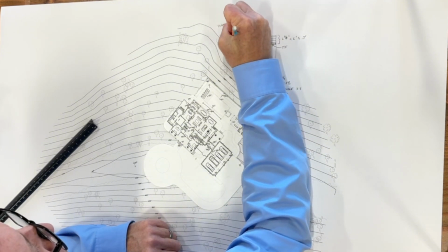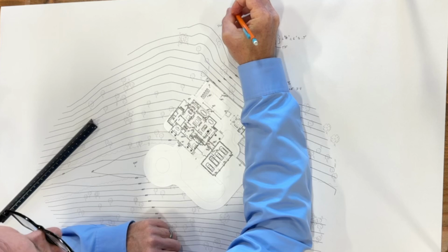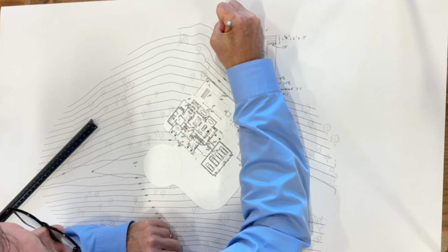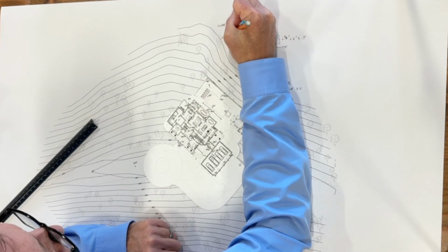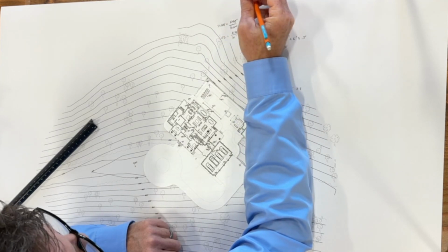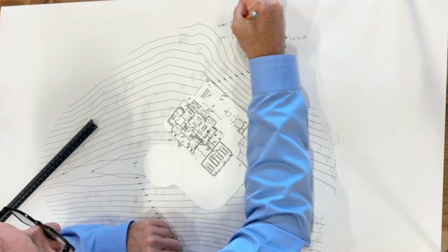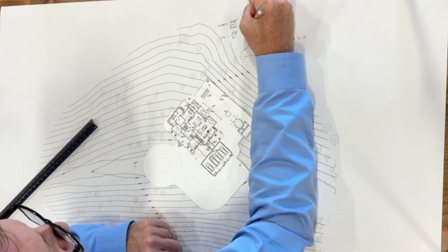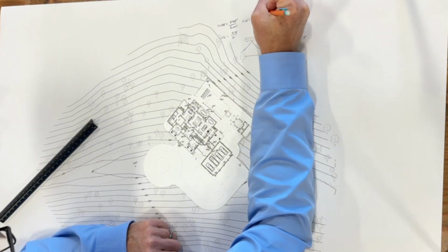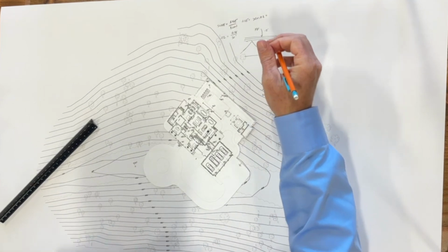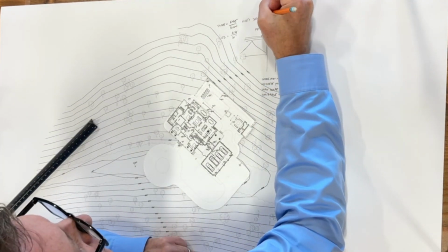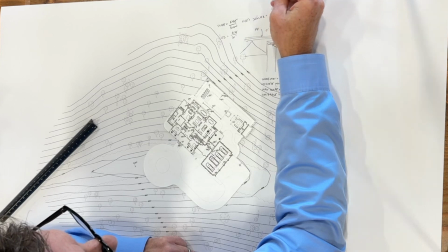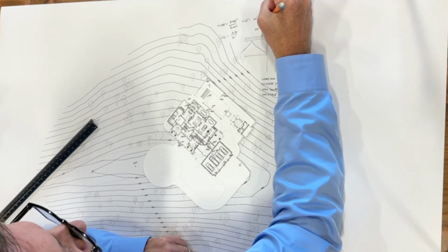So if we're going 30 feet, and we're going to say it's got to be 0.02 for the rise. So we're determining how far that has got to drop from there. So it's going to be 30 times 0.02. And anybody do that? Christian, you got that? Those 30 feet times 0.02 equals 0.6, okay?